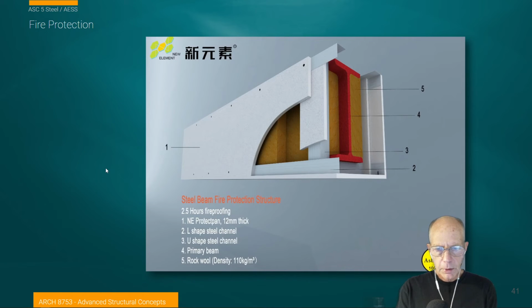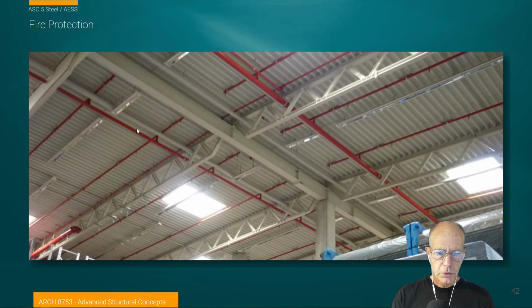And another way, and probably for sure not the way we would want to do it if we were making exposed structural steel, would be to insulate or cover our steel beams. And one of the best materials, a common way, is to cover them with drywall. So we can actually add thermal insulation, non-flammable, things like rock wool, and then cover them with gypsum board or cement board. Gypsum board is a really good material to give us fire resistance, and we can continue to put layer after layer above it in order to increase the fire resistance of the assembly that we're trying to construct.